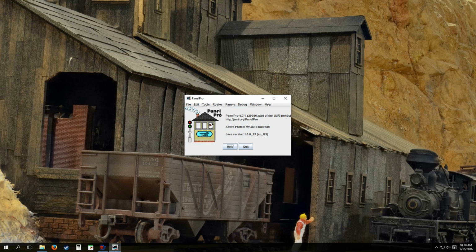So once you've got that in place, the best way to make a panel is to get your turnouts in place with the tortoises, servos, whatever you're using to control them operating, and have those decoders already there, and use your throttle or your command station and ensure that the throttle and the command station can actually communicate to that decoder. Once it's communicating to that decoder and it's actually turning the turnout, we can then go into JMRI.